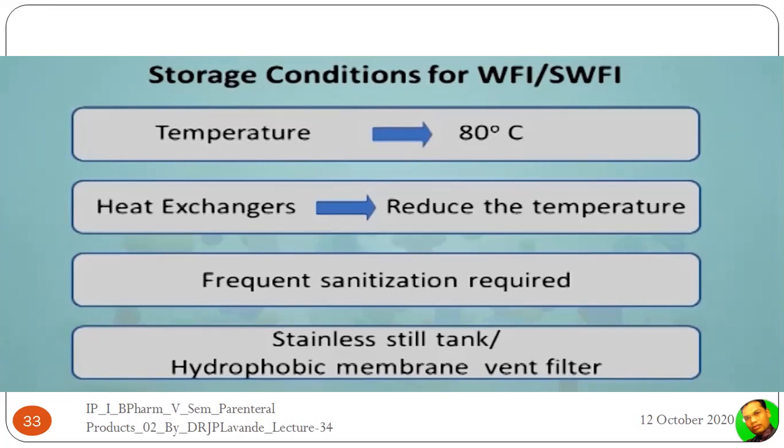Now, the water cannot be stored for more than 24 hours, so it needs to be frequently sanitized. Frequent sanitization is required because if it remains for more than 24 hours, there are chances of contamination or growth of microorganisms. The water for injection or sterile water for injection is stored in a stainless steel tank with hydrophobic membrane vent filters.